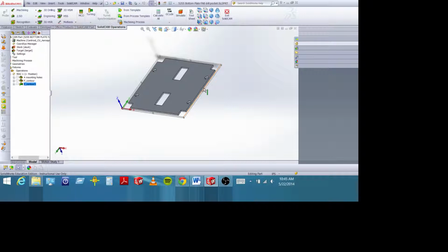Now that doesn't always work, especially with thin pieces or larger, longer pieces, because the material itself is wavy a little bit, on the order of thousandths. So as you get really close, within 4 or 5 thousandths, you could cut all the way through on these two edges and still have material on these edges. That way this thing's going to start flapping up and down, and then you'll get poor finishes and poor dimensional tolerance on these sides. So you can't always do this, but if it's small or thick parts, you can get away with it sometimes. So it's a method that you can use.